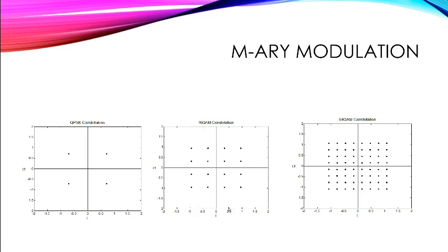In this slide, I show the constellation for the different M-ary modulation. As we can see, the QPSK modulation has more room for decision making. So this means that the BER of the QPSK is much better than 64 QAM, for example, because if we add noise to this symbol, even if the symbol is not located at the right position, we still have a very good chance to recover this symbol and to recognize it as the right symbol, and therefore having fewer errors.